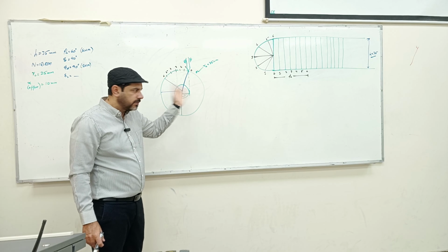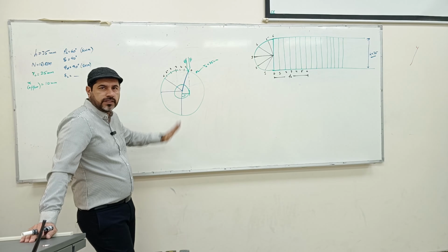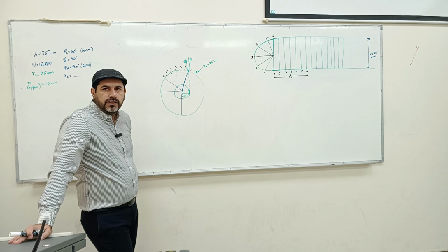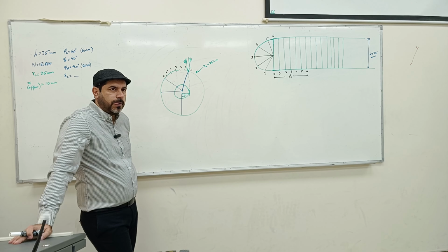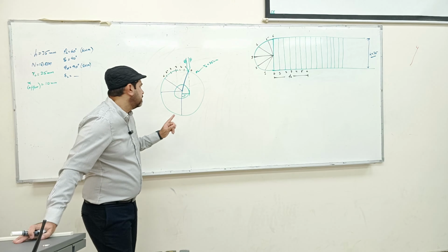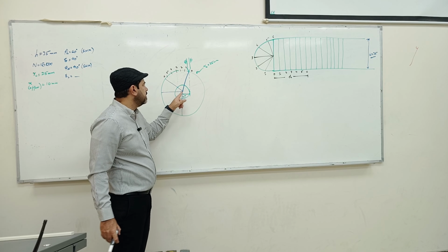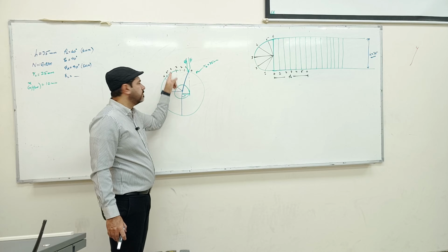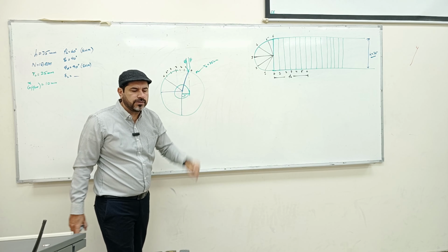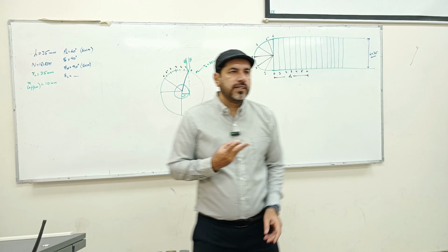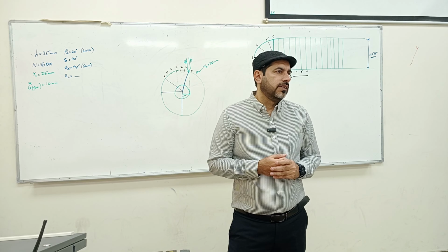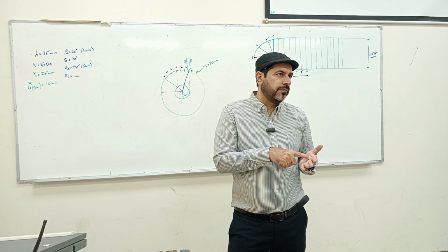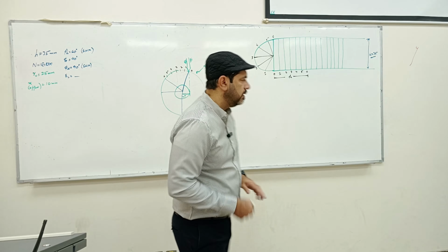I draw it a little bit away because the next thing I'm going to do needs some space. In the previous case, we joined the line from the center point to 1 and extended it, center point to 2, center point to 3. But here we don't do that, because we need two points to make a ray. This time we are going to draw tangents to the offset circle, passing through the points.